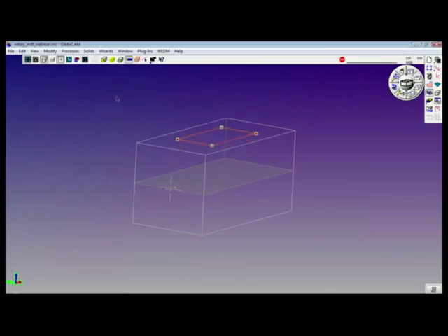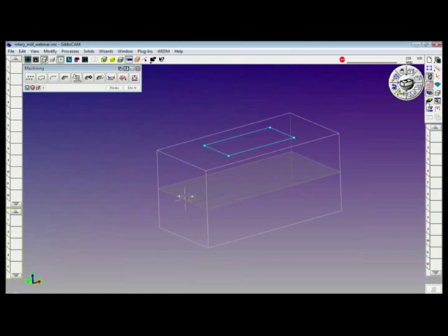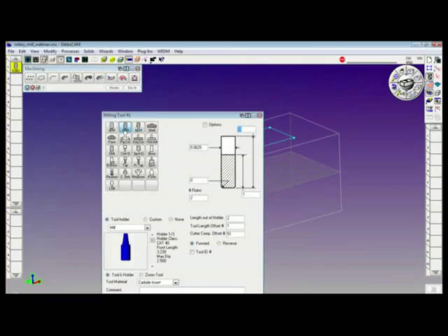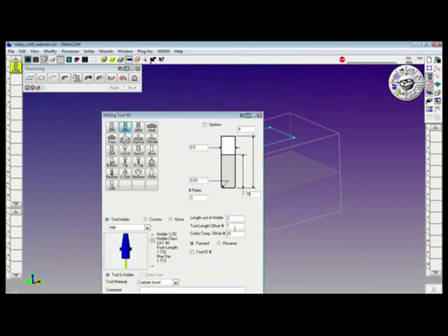All right, we got a simple shape here. Let's do some machining. Tool list, cam list. I'm going to create a tool. Simple tool. Finish end mill, 4 inches long, 0.5 diameter, 0.03 corner radius, 3 flutes, 1.75 length of cut. I'm going to use a tool holder, extended out of the tool holder 2 inches. Tool length offset number 1, cutter comp offset number 1.